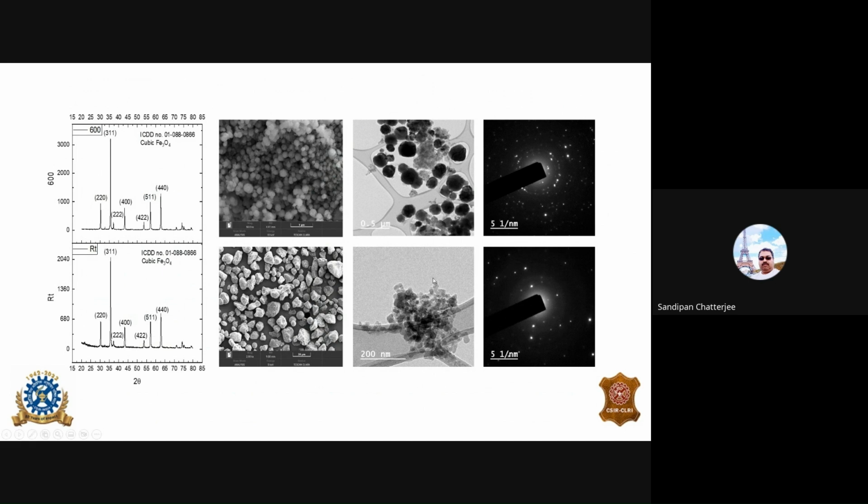And this is the TEM. When you study the TEM, initially for the native one without treatment, it does not show very clear pictures. But here it is very well revealed in the case of the calcinated one. It's quite expected because this styrene acrylic polymer is very tough in structure, so it does not allow the rays to go inside to study properly.